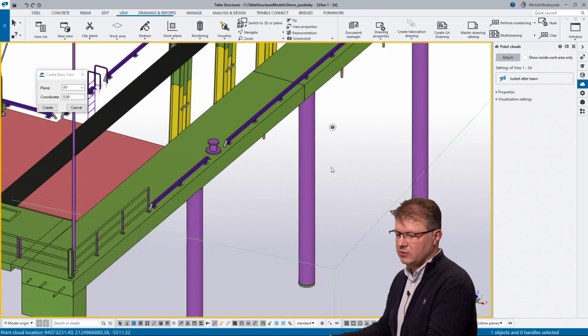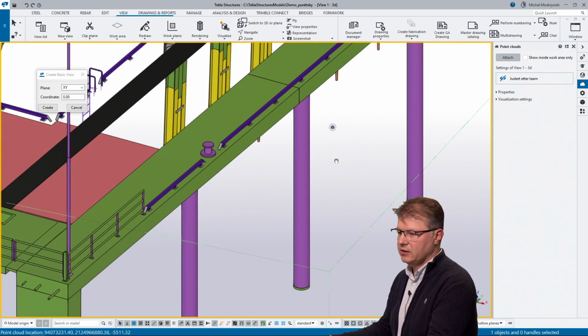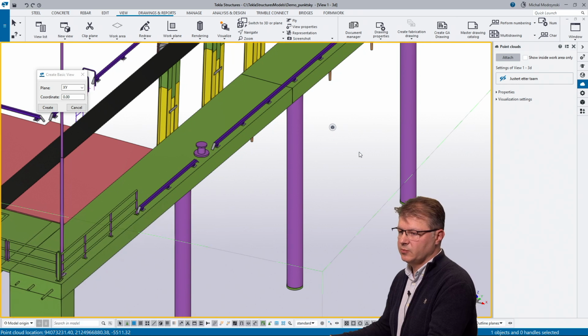Of course, this is not going to be created in a correct coordinate system. It's just going to be a local coordinate system, and I will show you how to manually maneuver it into the correct position in your model. So let us just import the point cloud.